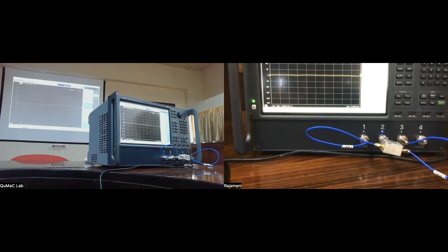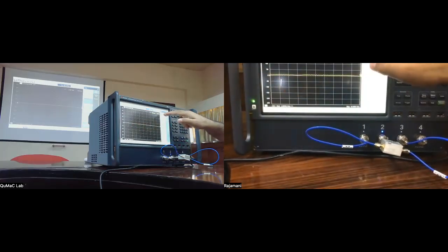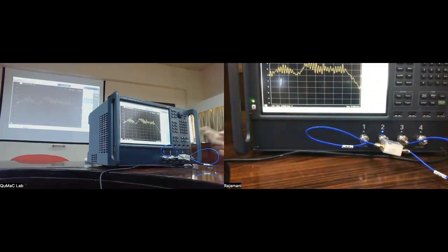If the device had some non-standard behavior, like a resonance, that will not get cancelled out. You would see that on top of this. You can see there is some overall trend changing with frequency, which is now a feature of this device's own phase response. But since this is a splitter, we expect it to have just some fixed phase here.